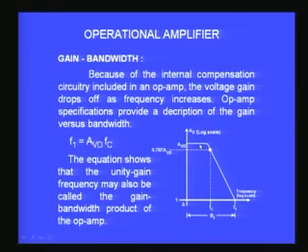This maximum gain multiplied by 0.707, wherever that gain is achieved, that frequency on the x axis will correspond to the upper cutoff.